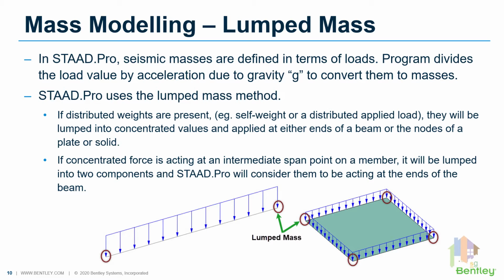Similarly, if you apply a concentrated load or patch load in any intermediate portion, that load is also converted to lumped mass and applied at the end nodes. After converting this mass to weight that is used in the seismic analysis, you have the flexibility to apply the seismic weight as a load, and the rest of the conversion is done internally.